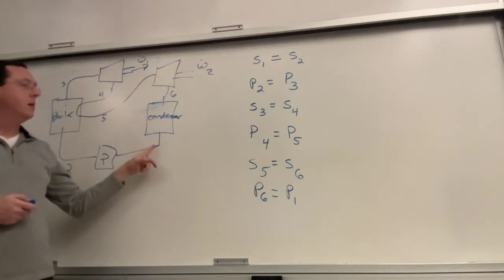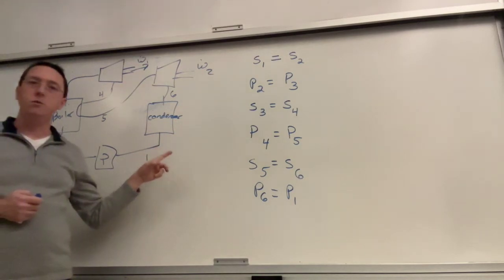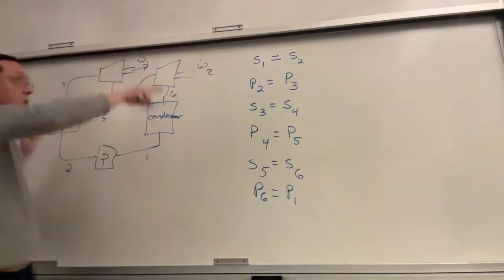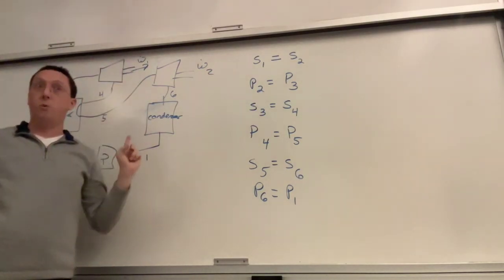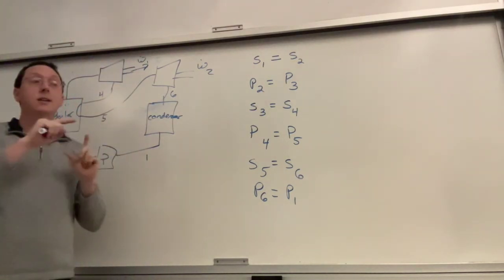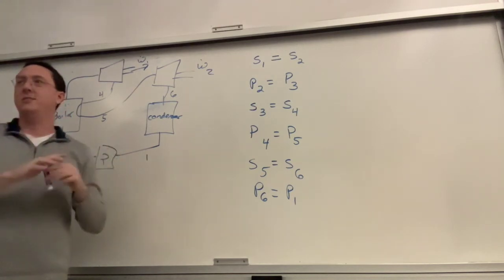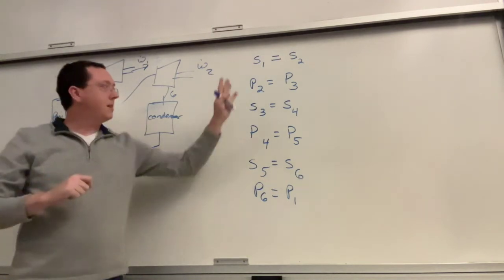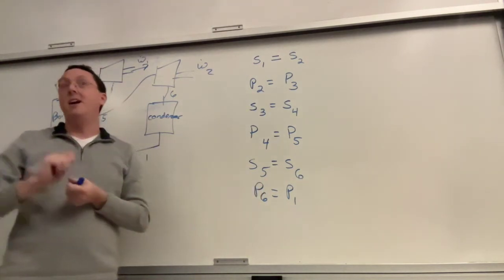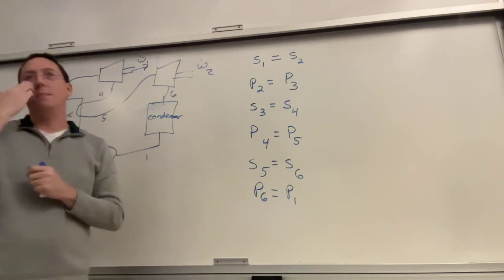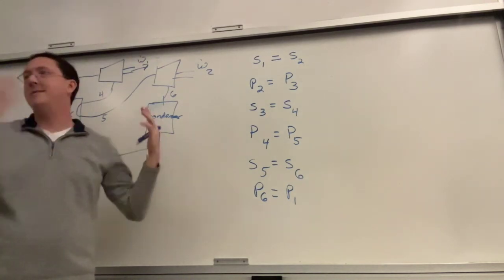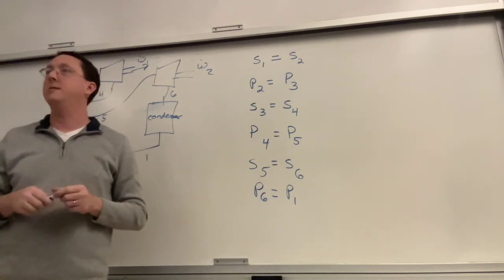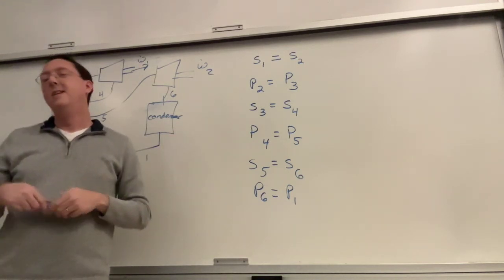So instead, what you can do is use efficiencies, not the cycle efficiencies, which are what we've talked about before, but what I'm going to talk about today at the end, called isentropic efficiencies, where basically you say, if it was isentropic, this would be true, but if it's not, the power out of a turbine is down, you only get 90% out, and so you work out what that means.